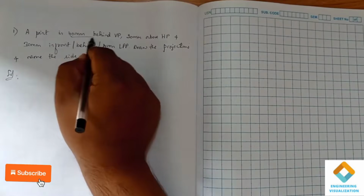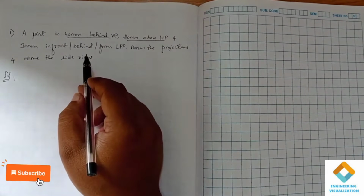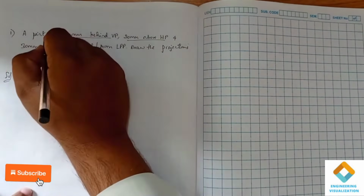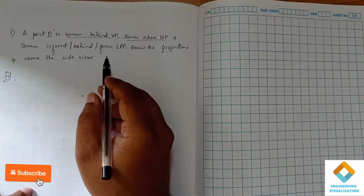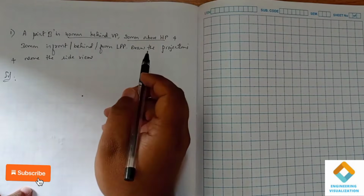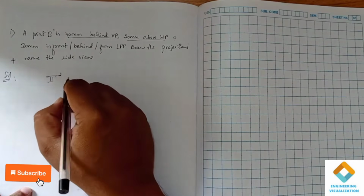First, identify in which quadrant the point lies. The point, point capital B, is 40 mm behind VP and 20 mm above HP. So it is in the second quadrant, behind VP and above HP.